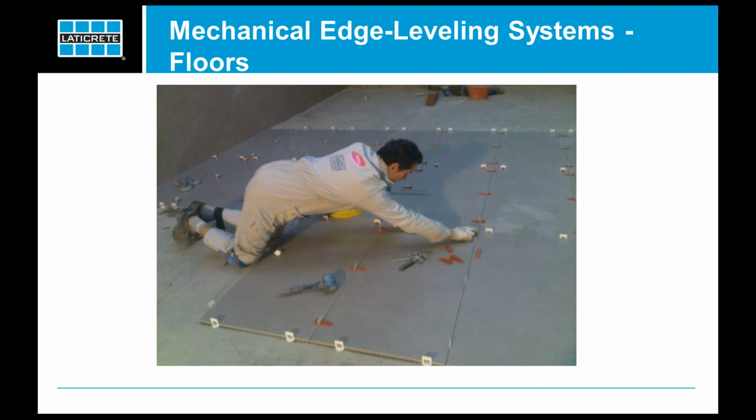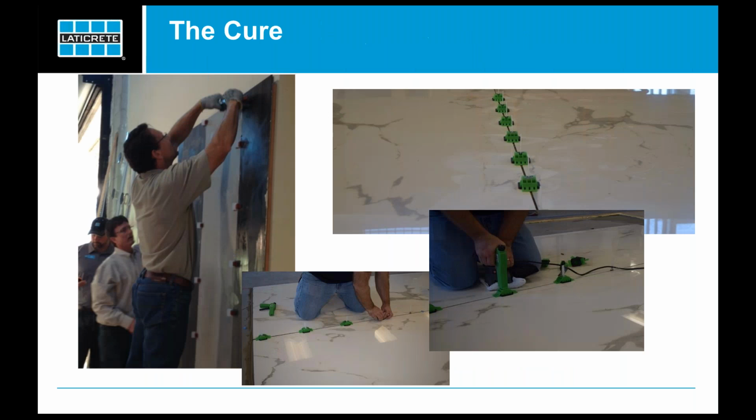Here's a standard thickness, large format porcelain tile. This tile is about maybe 3/8 to 1/2 inch in thickness. So they can also be used for standard thickness tiles as well. A little bit more tedious, but it really makes a big difference in minimizing lippage. So we strongly encourage their use, and they're also encouraged to be used in the standards that were created.